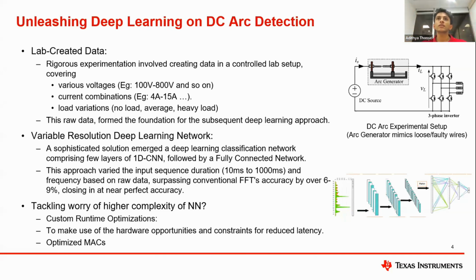Yeah. So a lot of these sample population cases are what we try out, and based on that we do neural networks. We try a few combinations of neural networks. Now, after all, you can have a really large network to solve any kind of problem. That will definitely work. But here, what we are trying to do is solve this using a neural network that is also fittable onto a microcontroller. That's where the tinyML part comes in. It's not just any neural network, it's something that fits into a microcontroller.